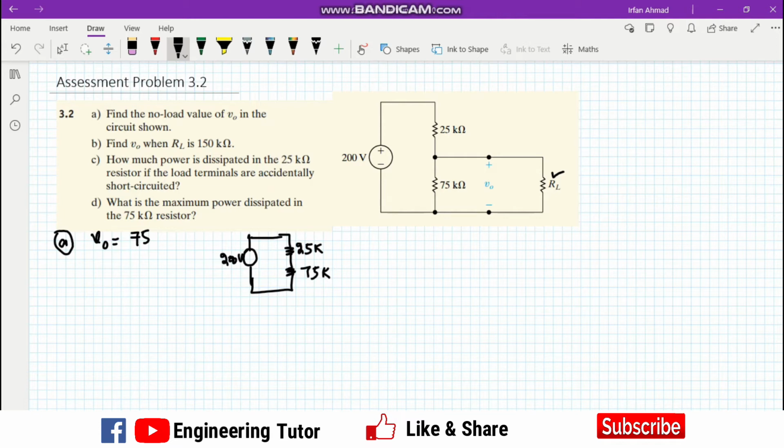Now to find the voltage here, which is V naught, we will use the voltage divider law. According to the voltage divider law, it is 75k divided by 25k plus 75k, multiplied by the total voltage, which is 200 volts.